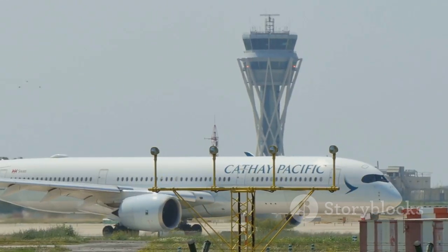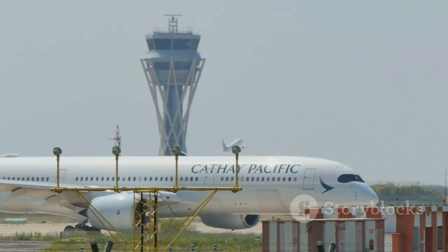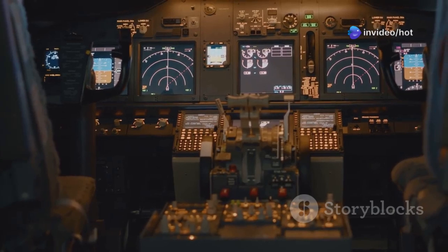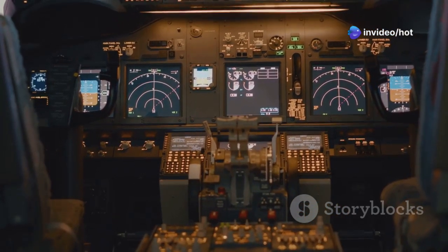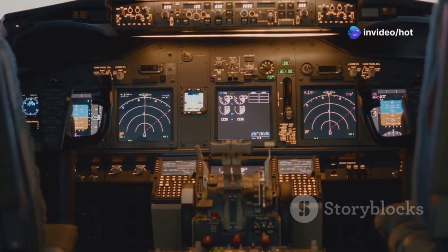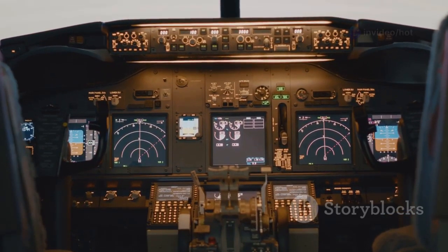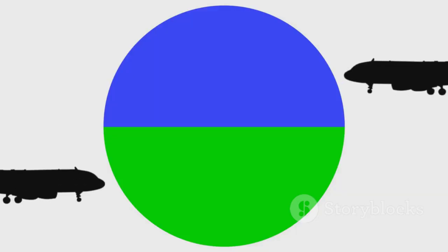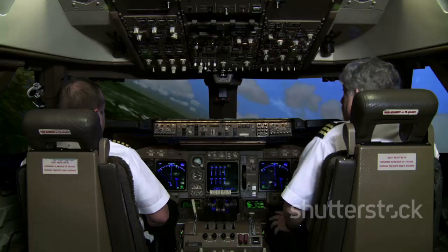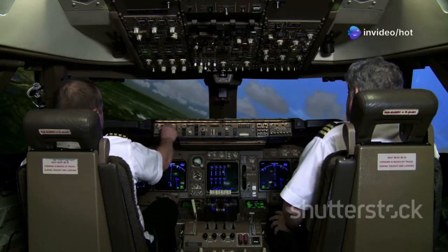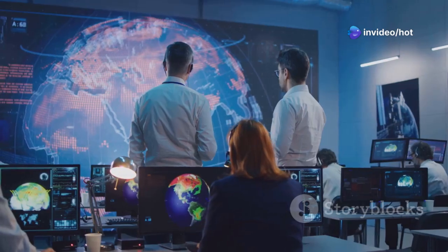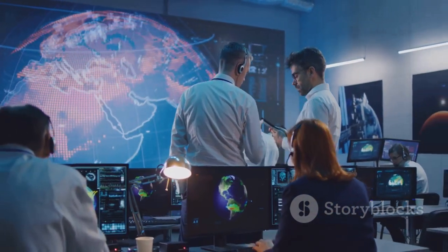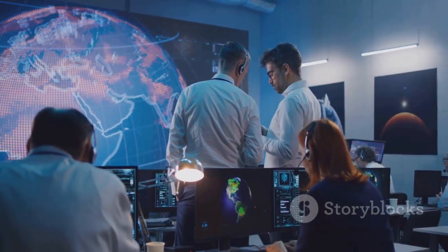One significant area of variation is reduced vertical separation minima, or RVSM. In RVSM airspace, typically between flight level 290 and flight level 410 inclusive, aircraft can be separated by only 1,000 feet vertically. Previously 2,000 feet was required at these high altitudes. RVSM requires specific aircraft equipment and crew training. While RVSM itself is a standard, its implementation details might vary, or the specific flight levels covered by it.